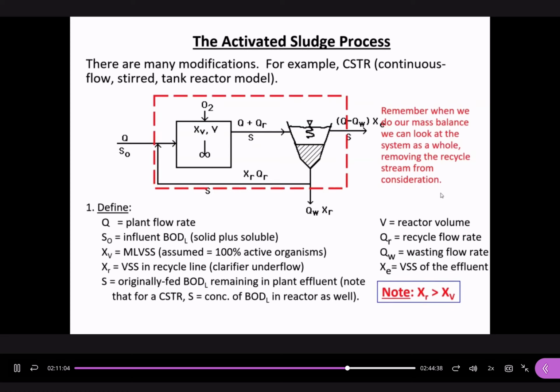So the in term, Q is flow, times concentration. What concentration? It's X in, right? That is how much microorganism is going into the system, going into the red box. Q times X in. Flow rate times concentration. What is X in? It's 0, right? 0 is our assumption because X in is very small. So this is 0.